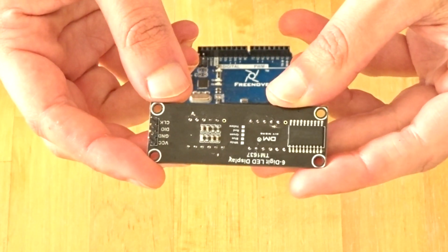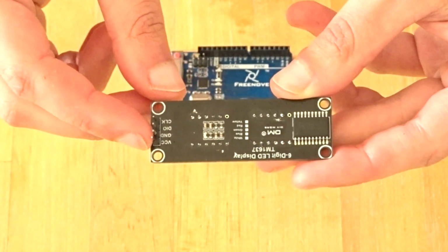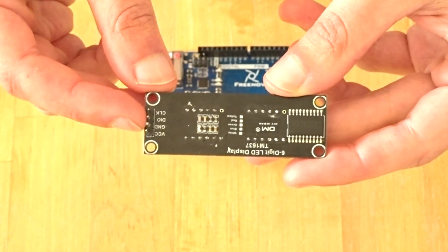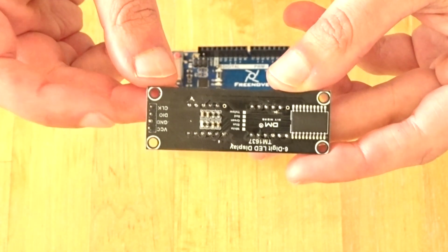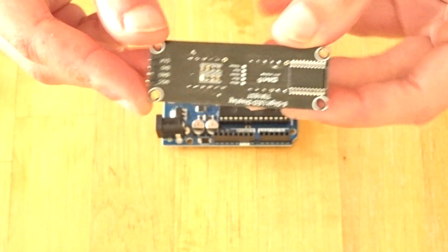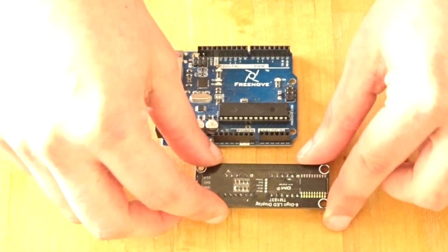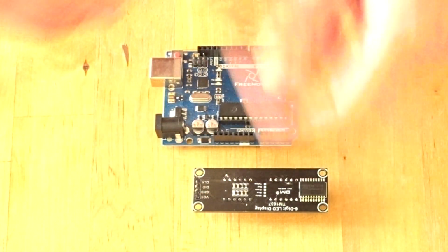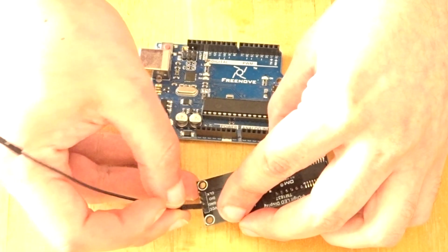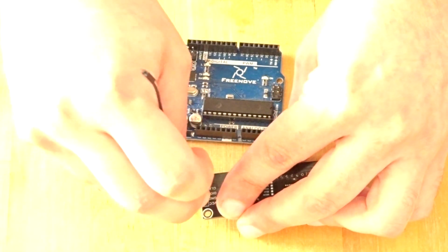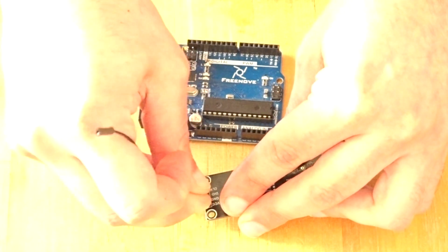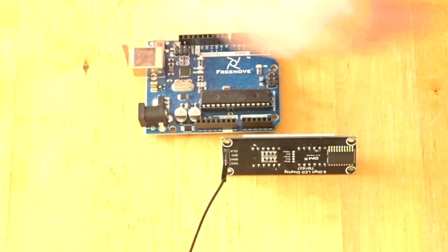Now let's start by wiring our screens to the Arduino board itself. Now for the screens, they have pins, so we're going to be using the male to female wires, and they are clearly marked VCC, ground, DIO, and CLK. Now the VCC and ground speak for itself, which is going to be the 5 volts and the ground wire, and we're just going to slide them over it and stick them into our breadboard because we need a shared common ground line.